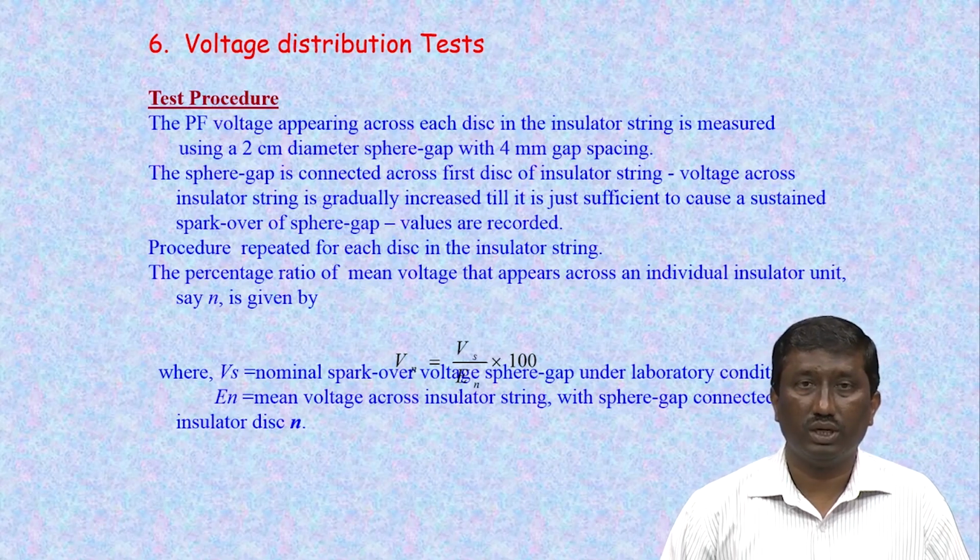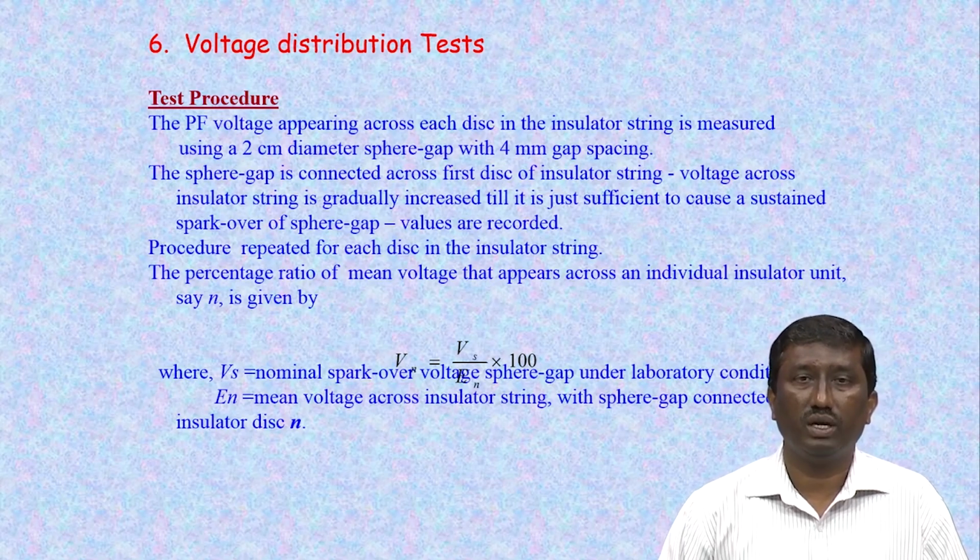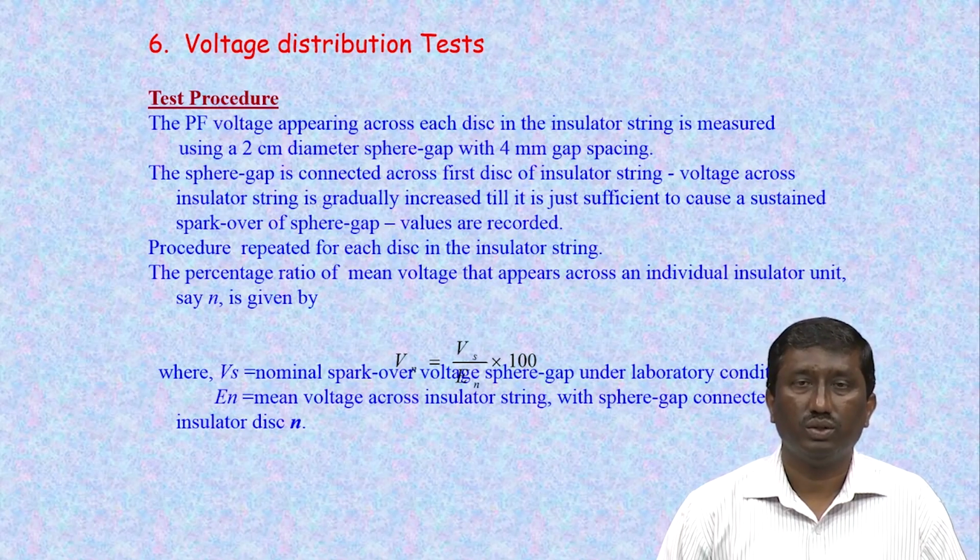You know that ceramic disc insulators are connected in cascade in the transmission lines, whether it is an I suspension, double tension or a V suspension string. We know that for 400 kV we have anywhere between 23 to 25 insulators cascaded. Similarly, for 765 kV we saw 35 to 40 insulators in cascade. These insulators typically have a capacitance ranging from 40 to 60 pF for each disc. Connected in cascade, the voltage distribution from the line end up to the ground end has to be